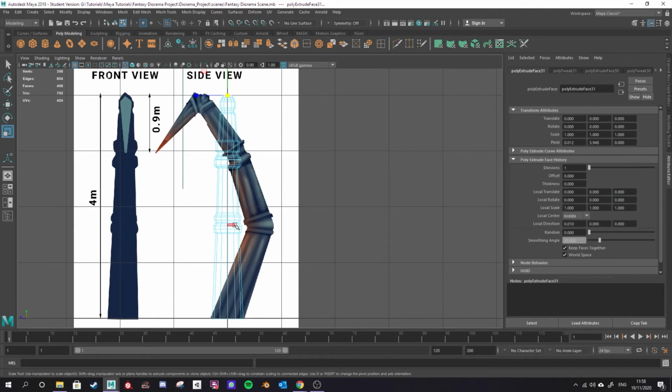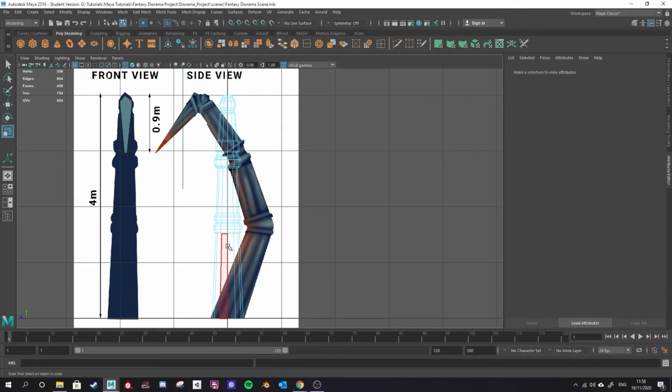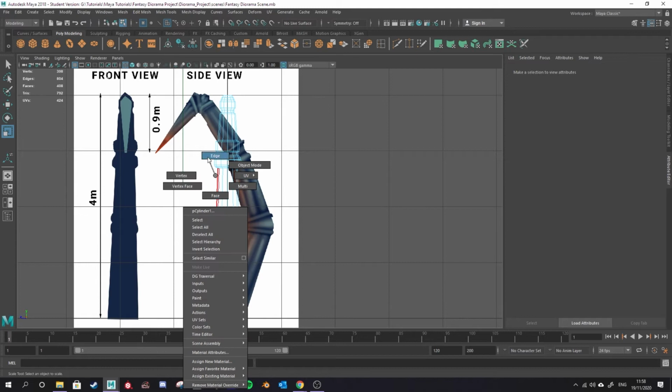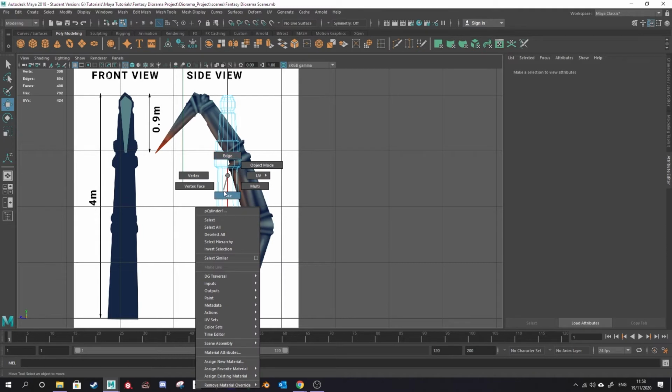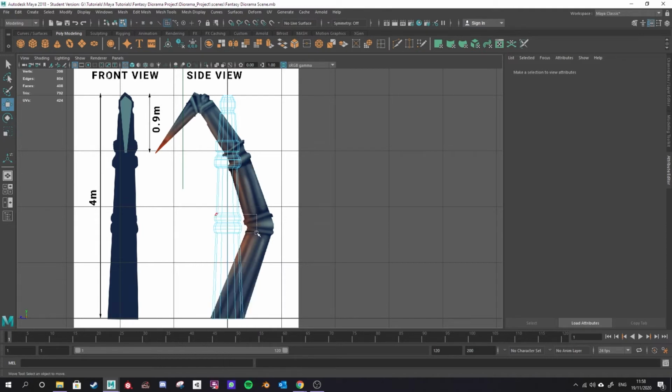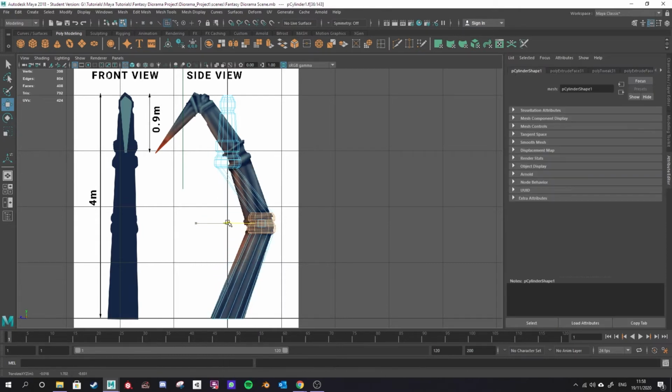Now here's where the extrusion workflow can be tricky, is now that I've created some complexity into my shape, moving all of these edges can be quite tricky. So I would need to use edge or face selection. Just got my W tool selected there, face, I'm going to drag around these. So I would need to start moving these parts into position.